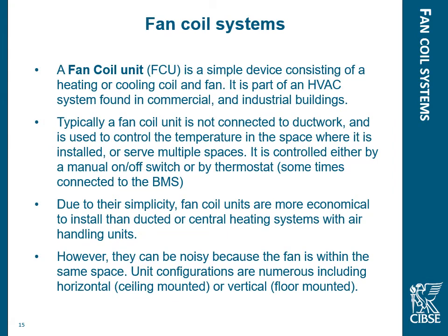A fan coil unit is a simple device, consisting of a heating and cooling coil and a fan. The fan coil is typically not connected to the ductwork. The ductwork just feeds fresh air into the zone. Due to the simplicity, fan coil units are more economical to install than ducted or central heating systems with air handling units.